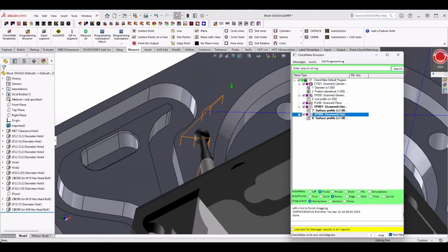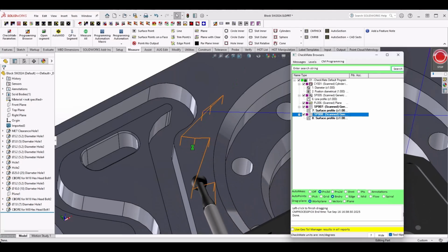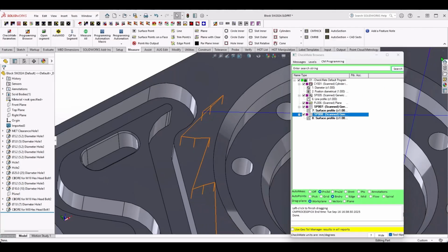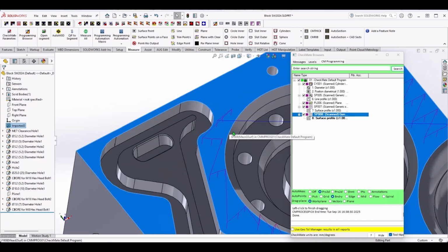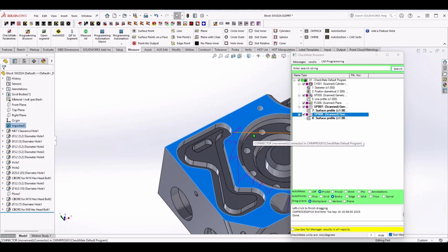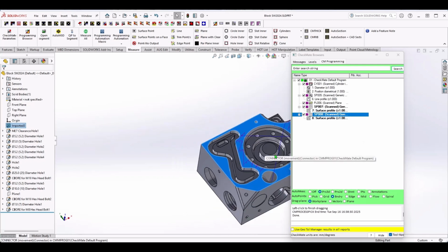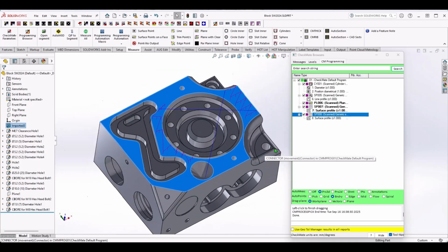That direction is defined by the direction from this point to this midpoint. These two just define the width. Now, it's important to keep them roughly perpendicular, because if it's a curved surface, then it also defines the curvature. And the Renishaw UCC controller will crap out on the CMM if it's too far off.